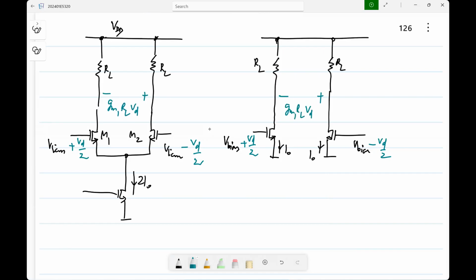What is the difference between these two circuits? What are we gaining from this extra transistor at the bottom in the first circuit? They seem to give you the same output, right? What is the difference? Common mode. What is the difference in the common mode? Very different bias. Well defined. The other one also has well defined bias. No, I choose the value V bias, that's all.